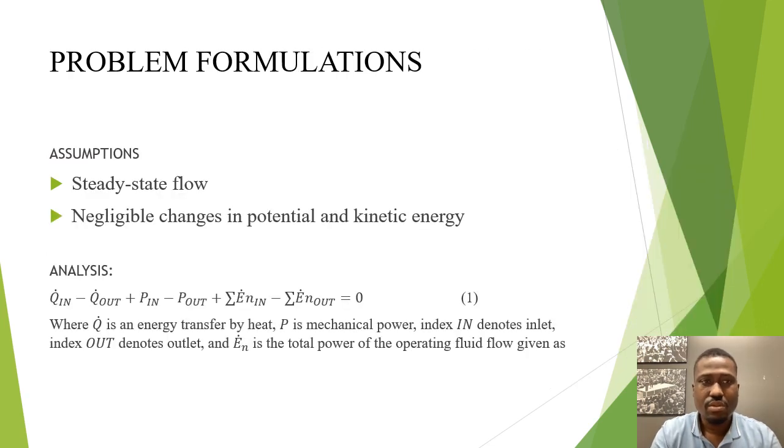To go forward, we have to make some assumptions in this turbine. One, that the process in this turbine is a steady state flow, and also that the potential and kinetic energy changes in this turbine are negligible. It is also important to note that we are not assuming that there is no heat loss or heat gained